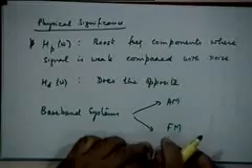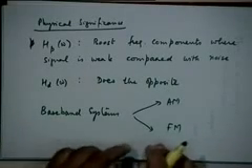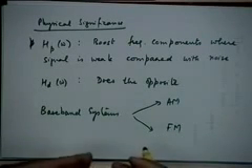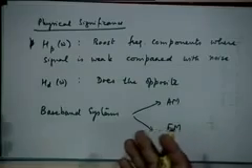But for FM, this concept of pre-emphasis and de-emphasis filtering is particularly important in view of the fact that we already discussed when we discussed in the context of tonal interference, for example, right? We discussed it in more detail, and in view of the fact that the threshold is likely to be there, you like to make use of every avenue that is possible to make sure that you remain above the threshold value, right? So you optimize the performance to the extent that you can.